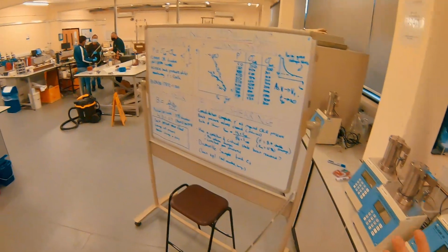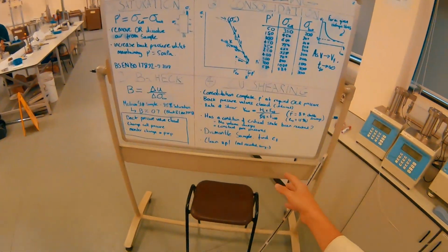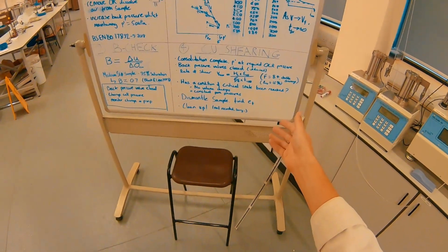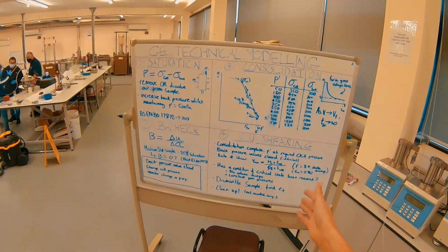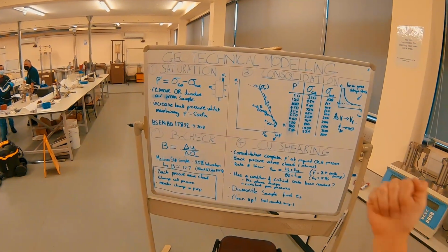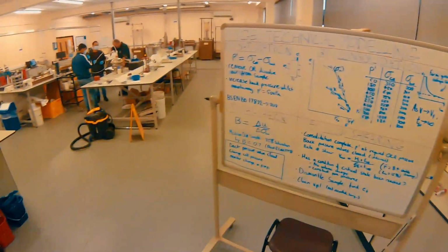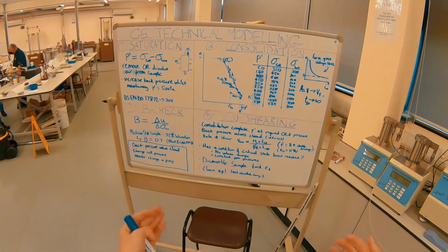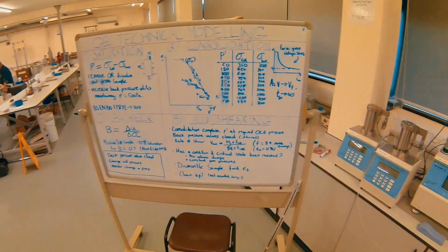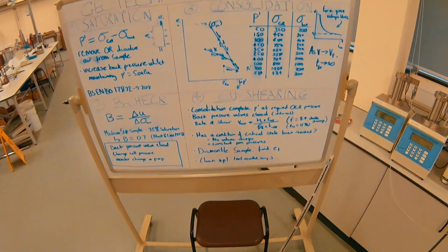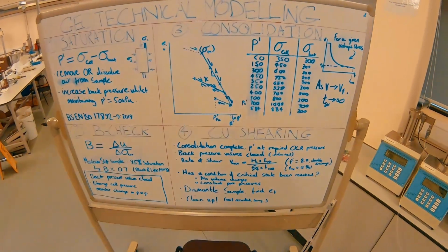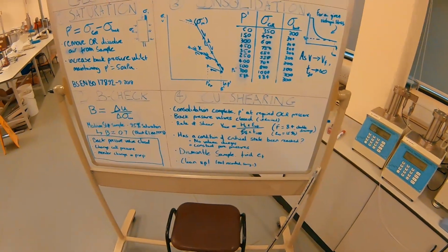So in the next phase, now we're at the correct p dash for our over-consolidation pressure, we need to think about doing an undrained shear test. And to do that, we need to come up with a shear rate. Just a little primer on one of these things before we move on to the next video, just so you can think about these issues.